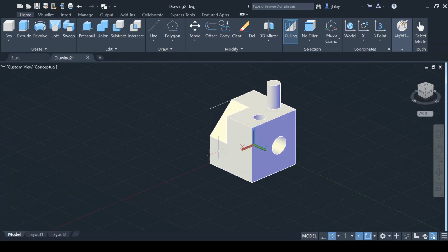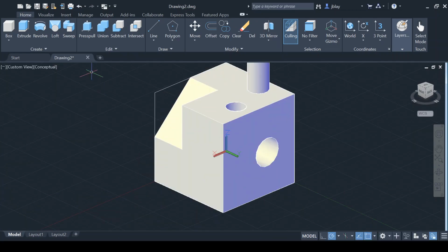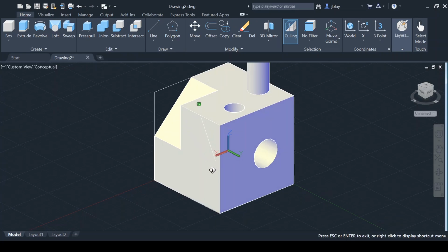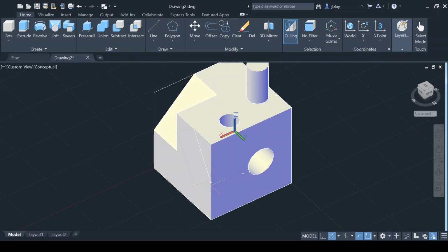One last thing to be aware of before we move on here. You need to have a bounded area of sketch, meaning you can't utilize the corners of the shape, the edges of this solid, to help you. So let's say I'm drawing a triangle here. Notice that I only drew 2 lines. I didn't draw the one up top. And if I hover over the shape, you can see that there are only 2 lines. If I try to press pull this, it doesn't treat it as an enclosed space. It just senses that overall shape. You need to include that last line to create a bounded area that is sketched. Once you do that, you should be able to pull it.